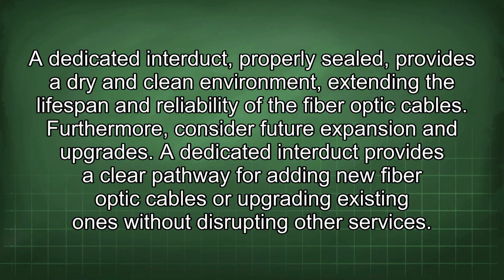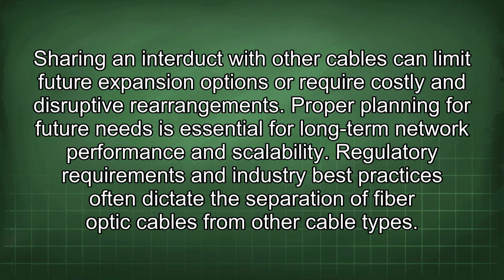Furthermore, consider future expansion and upgrades. A dedicated interduct provides a clear pathway for adding new fiber optic cables or upgrading existing ones without disrupting other services. Sharing an interduct with other cables can limit future expansion options or require costly and disruptive rearrangements. Proper planning for future needs is essential for long-term network performance and scalability.